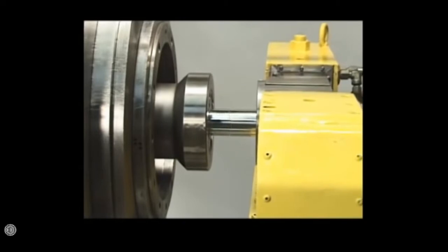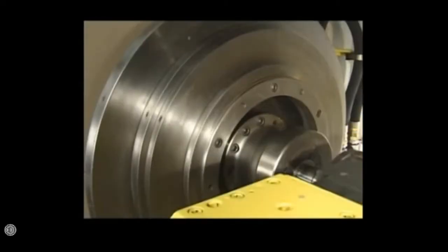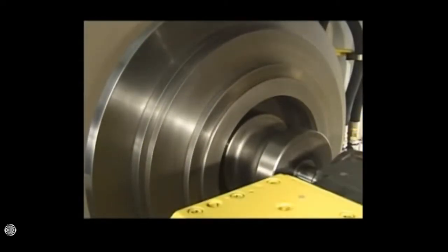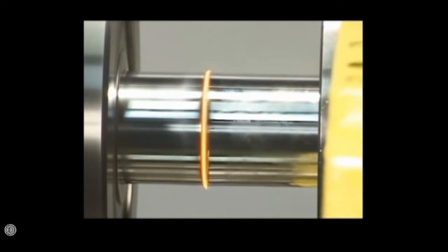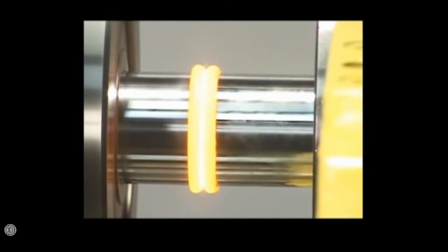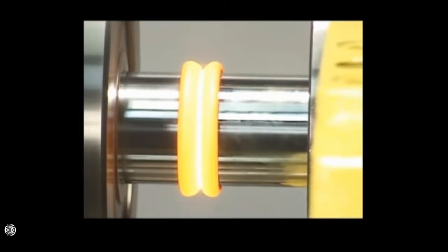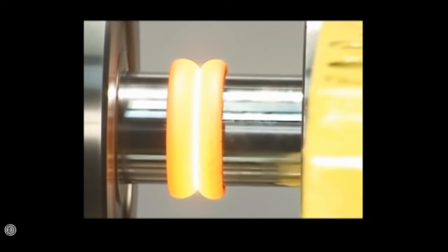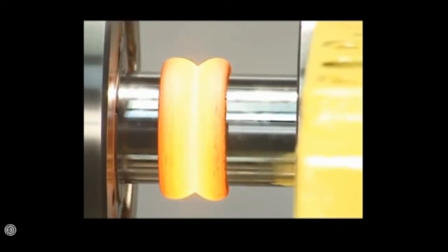One piece is held stationary, the other is rotated rapidly on a spindle chuck attached to a flywheel. When the flywheel reaches a predetermined speed, it is disengaged and the freewheeling piece is forced against the stationary piece. Friction between the parts heats the abutting surfaces to forging temperature. Just before rotation ceases, the two pieces bond automatically. When the flywheel stops, the weld is complete.